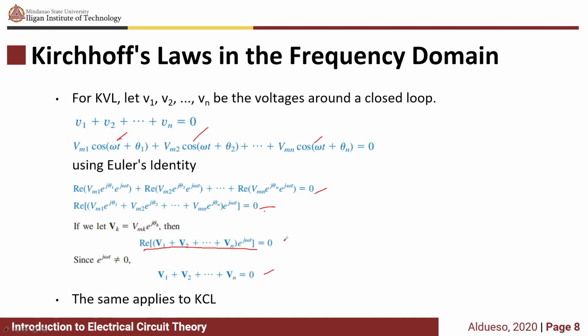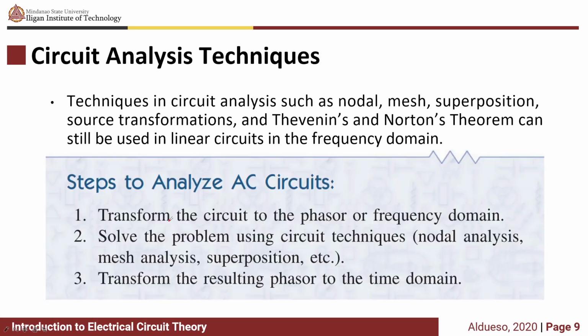So we can apply Kirchhoff's laws in linear AC circuits, the same as with DC circuits. The same applies with KCL. Techniques in circuit analysis such as nodal, mesh, superposition, source transformations, and Thevenin's and Norton's theorems can still be used in linear circuits in the frequency domain.